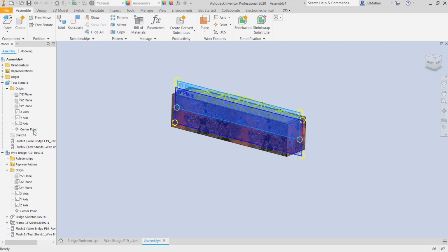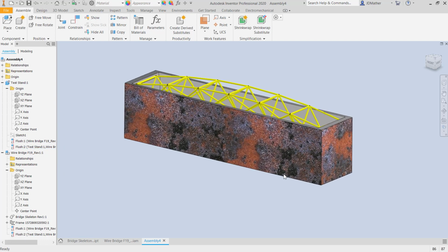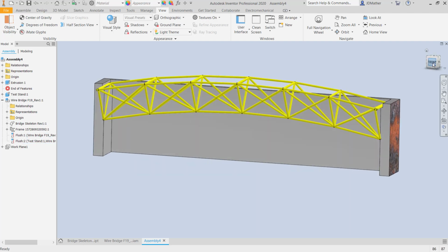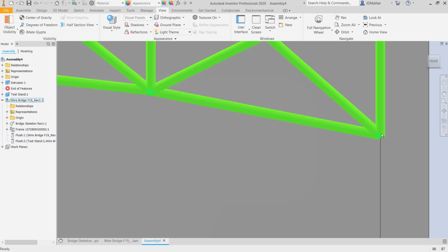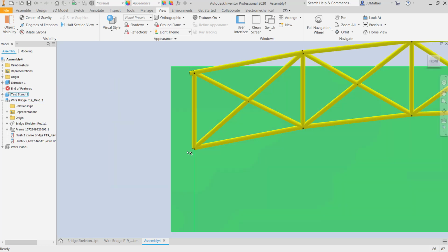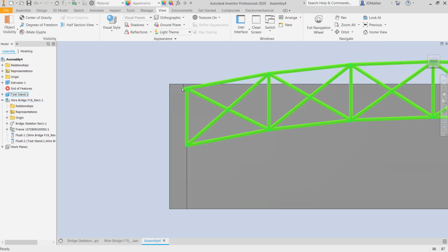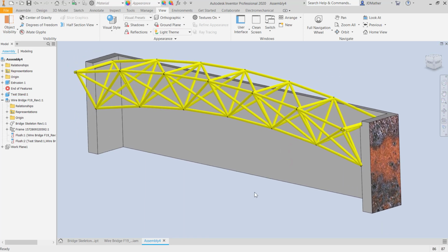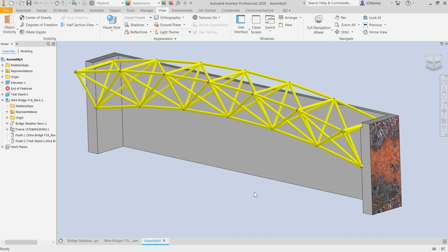So I'm going to cut away the front half of the test assembly so we can see how this fits. Now I went a little bit too far on this, so I need to actually go a 1/16 of an inch shorter this way and a 1/16 of an inch shorter this way so that it will fit into my test assembly. So that's one good reason for doing 3D modeling, is you can find little mistakes like that before you get the model all welded up and then find out that it won't fit into the test assembly.